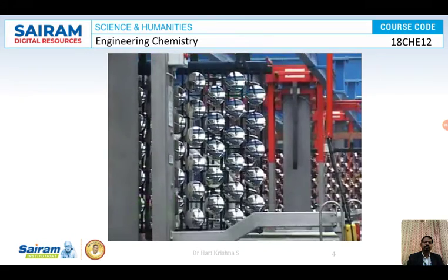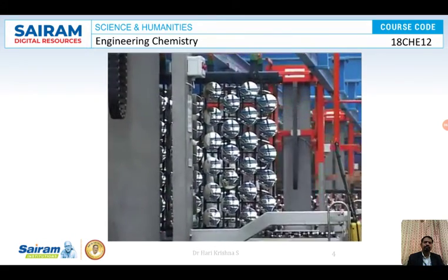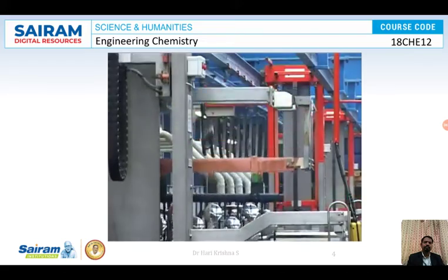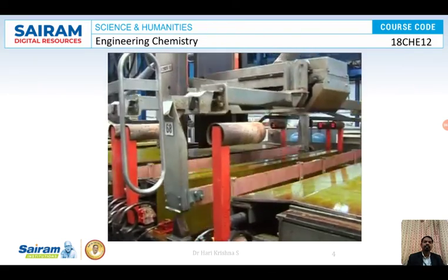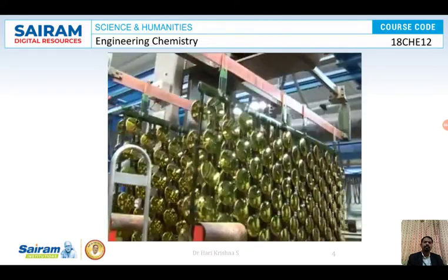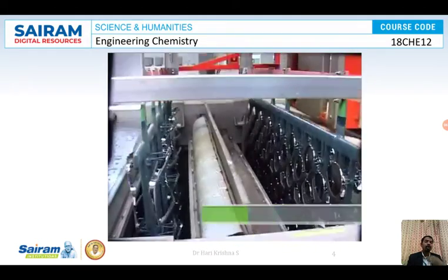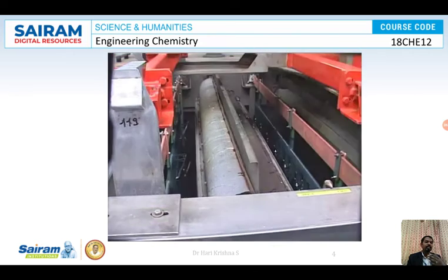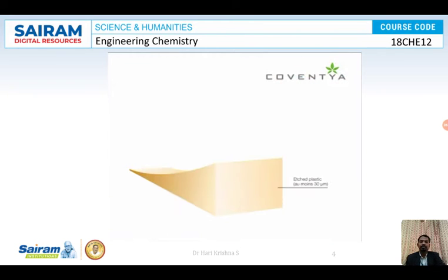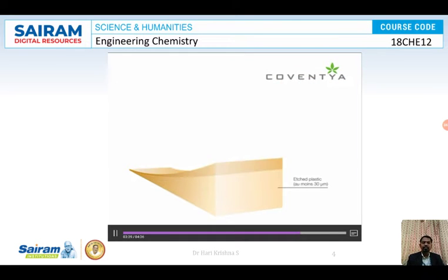In automotive industry applications, multiple layers of different types of nickel deposits are utilized to further increase the corrosion resistance of the plated plastic. The final chromium layer deposit of 0.1 to 0.2 microns thickness provides corrosion and anti-tarnishing protection for the surface, while giving the surface a bright decorative aspect. It also provides good shock and abrasion wear resistance.